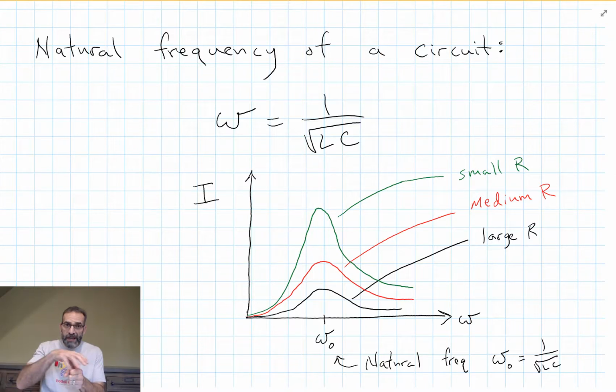When that coil of wire goes over a piece of metal, it changes the inductance. It's like putting an iron core into a coil of wire. You greatly change the way that coil of wire responds to current. You change the inductance. When you change the inductance, the resonant frequency changes and the circuit doesn't respond. The current in the circuit drops way down because you're not at the resonant frequency anymore, and that can be detected. Another example is tuning an old radio to a radio station.